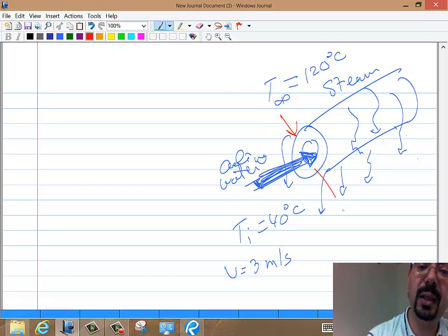Again, he didn't say, is it the inside diameter or the outside diameter? And he never said what kind of pipe it is. So same trick. We don't know the dimension. He didn't give us the key. There is no way we calculate the conduction resistance. So we'll just assume neglected conduction resistance. Neglecting the conduction resistance. All right?